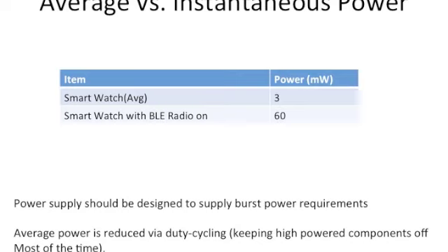So this is one of the most, shall we say, effective ways of reducing power, what is called duty cycling, right? It's very common sense, no rocket science, but it works. You keep things off and turn them on only when you need to. And the process of automating that, how do you intelligently keep things on and off and so on, that can become quite sophisticated. And so there could be a lot of interesting algorithms and so on, which might have to be developed to intelligently turn on things only when you're required to do so.